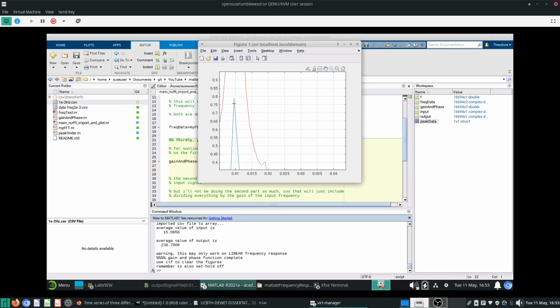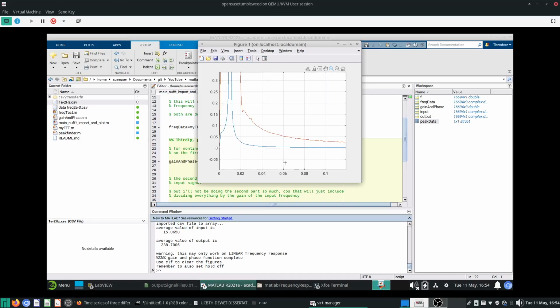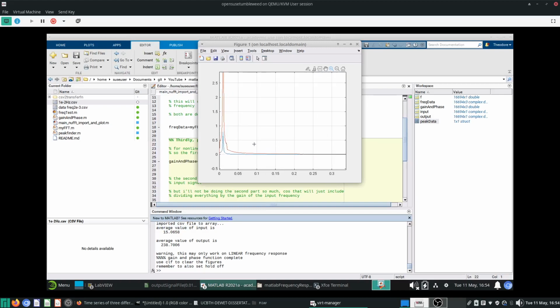But this is our oscillation of the input, and you look at the output, the amplitude here is about 6 in those so-called dimensionless units, and this is 6 degrees C. Now of course there are other frequencies over there, but that's okay. This looks more or less like a linear system. So now let's try a few different wave inputs and see what happens.